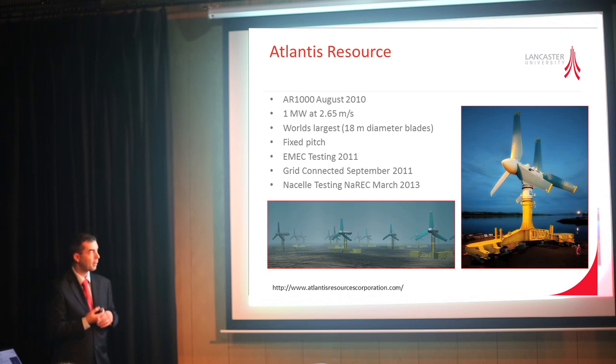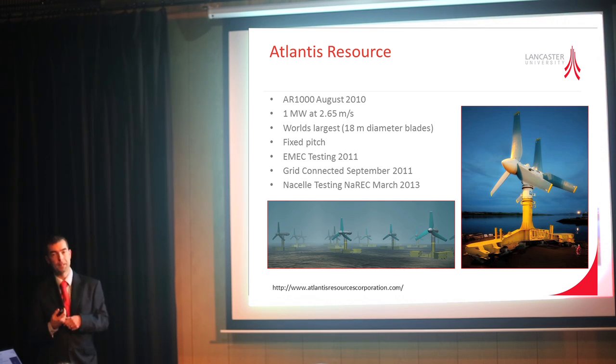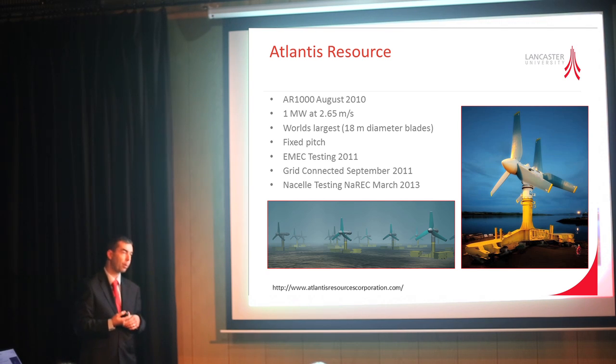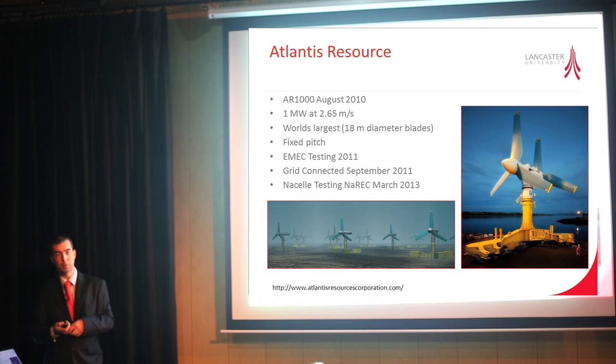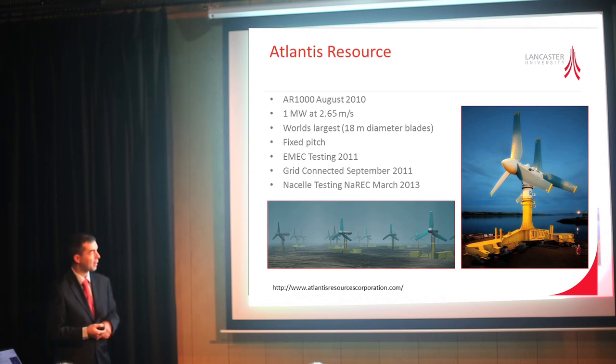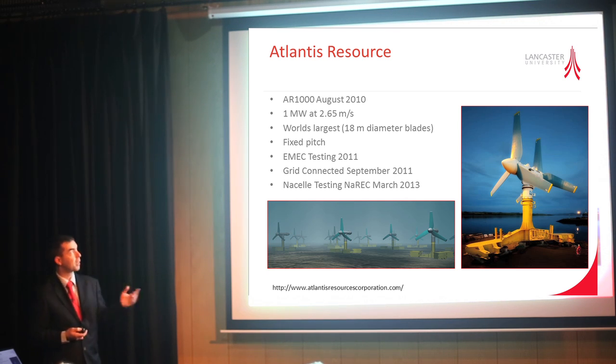When they put it in the water, after a couple of weeks the blades broke. They weren't expecting the load that they got. Similarly, Marine Current Turbines have had blades break. Open Hydro have had blades break. I think every manufacturer that's put a reasonable sized device in the water has had something break on it. Yeah, we're still learning. We're still trying to get it right. I think one of the messages that they've got from that is the twin rotor system isn't particularly reliable. They get a lot of fatigue occurring on the trailing rotor. So they're therefore looking now at single rotor devices similar to the Alstom device that we've just looked at.